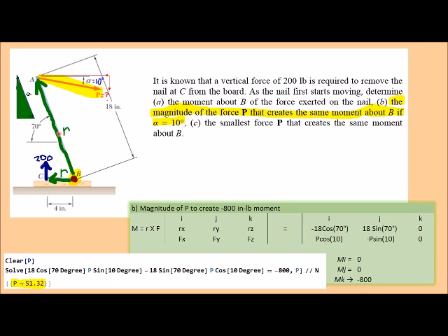And that's the point of a crowbar. That's the point of a lever arm, right? You have this nice big lever arm, and you can pull it with a very small force here. Only 50 pounds here creates a big 200 pounds over here. So that's a nice little mechanical advantage going on right there. And you can see that advantage, 4 to 8, okay? So that lever arm mechanical advantage translates into a force mechanical advantage, 50 to 200.